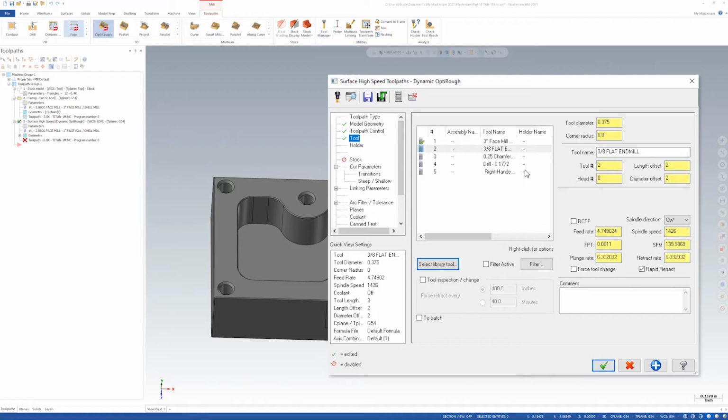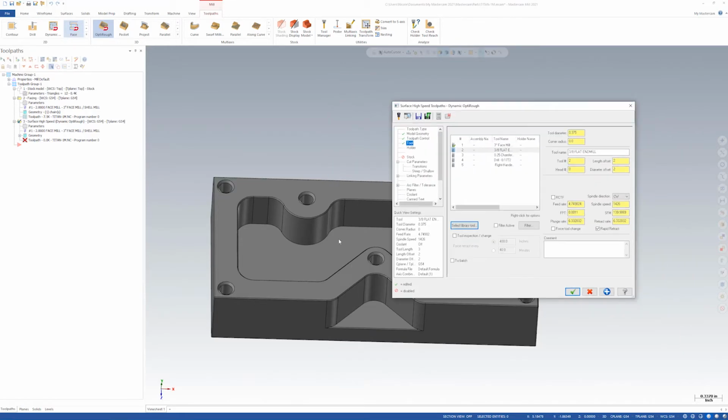That way we don't have to mess with a whole bunch of different finishing versus roughing tools, but just so that you know, typically when you're running production parts, you're going to have a roughing end mill and a finishing end mill, and the roughing end mill is going to be pushed a lot harder and faster, whereas the finishing end mill is going to be more for the delicate finishing and slower speeds and just dialing in the features of the part.